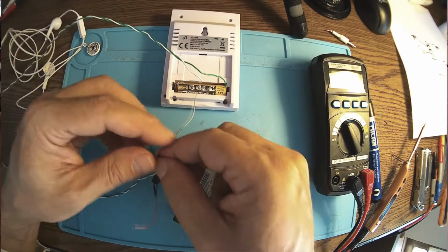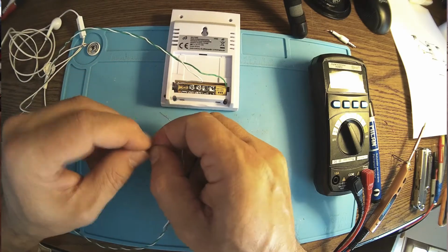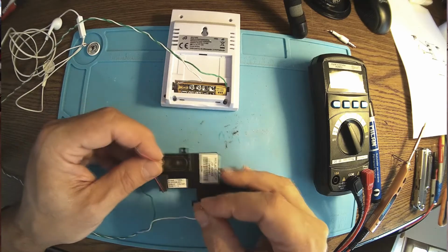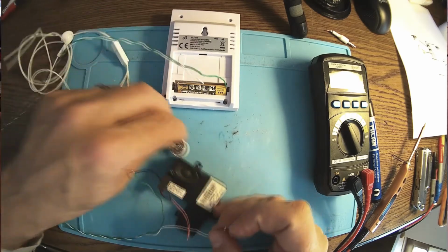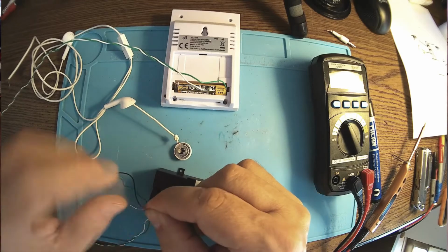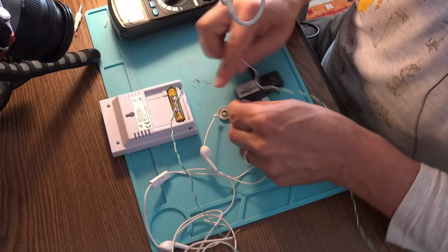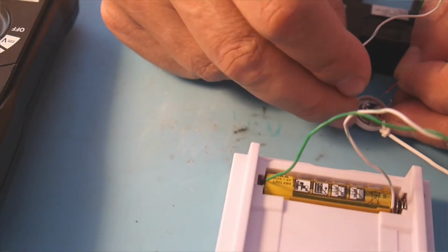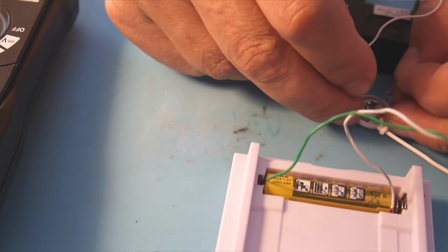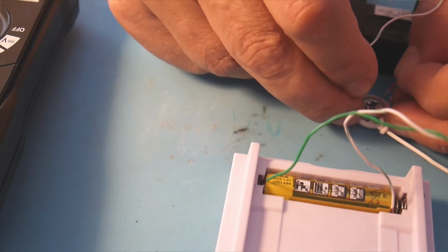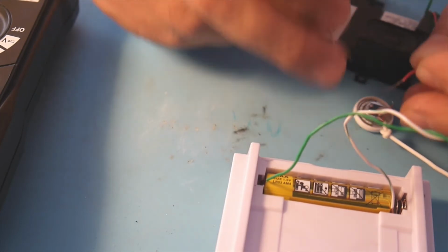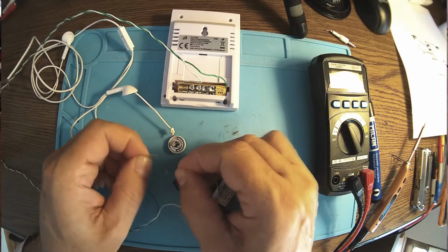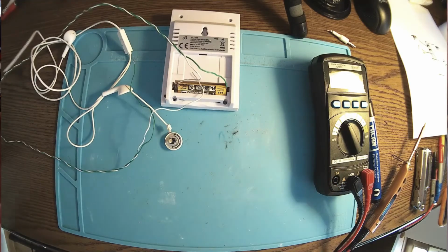Once again, you just connect the battery in series with a good headphone. Here we go. Of course, we check for the sound before. Okay, we are good to go. And now let me see if I can check the little headphone too. Just connect this to the headphone connector there. We should hear the sound. I can call this a kind of acoustic continuity tester. Very simple to improvise.